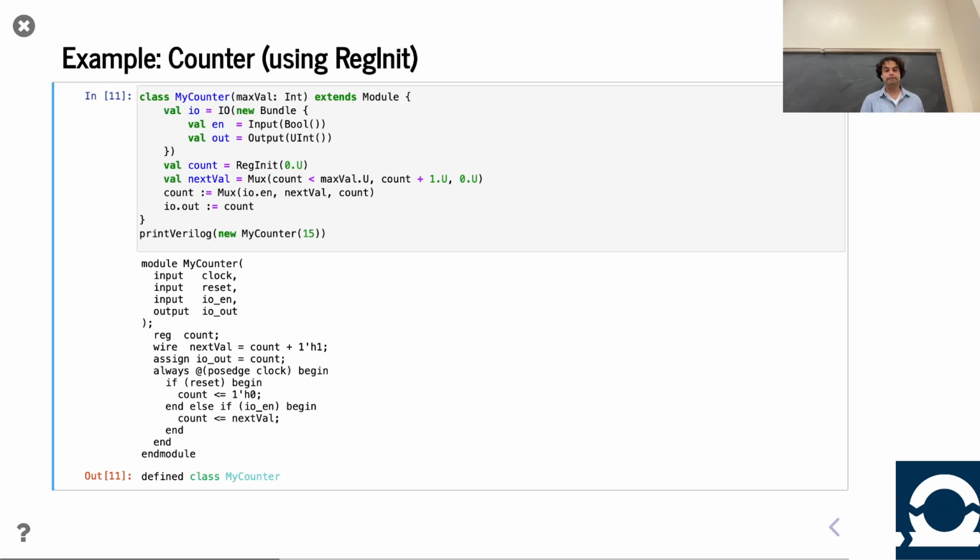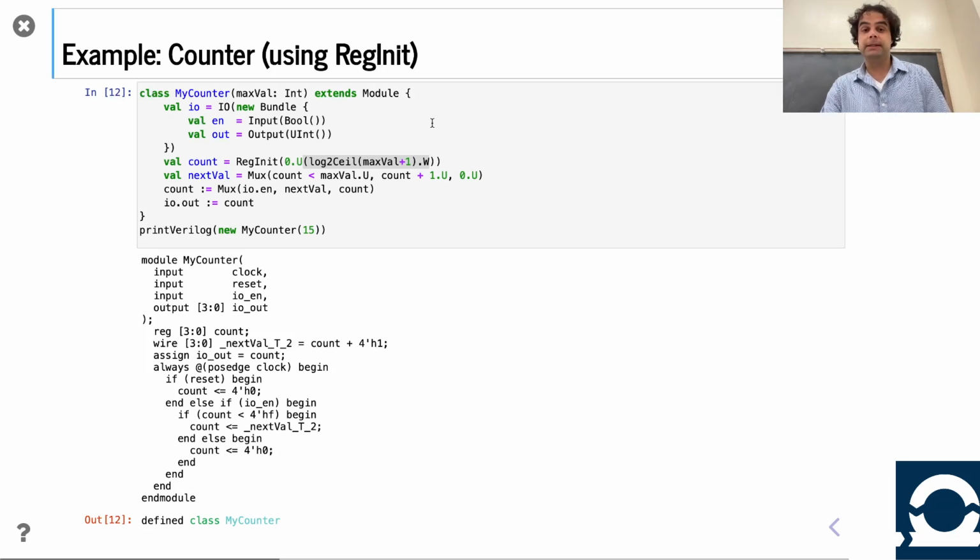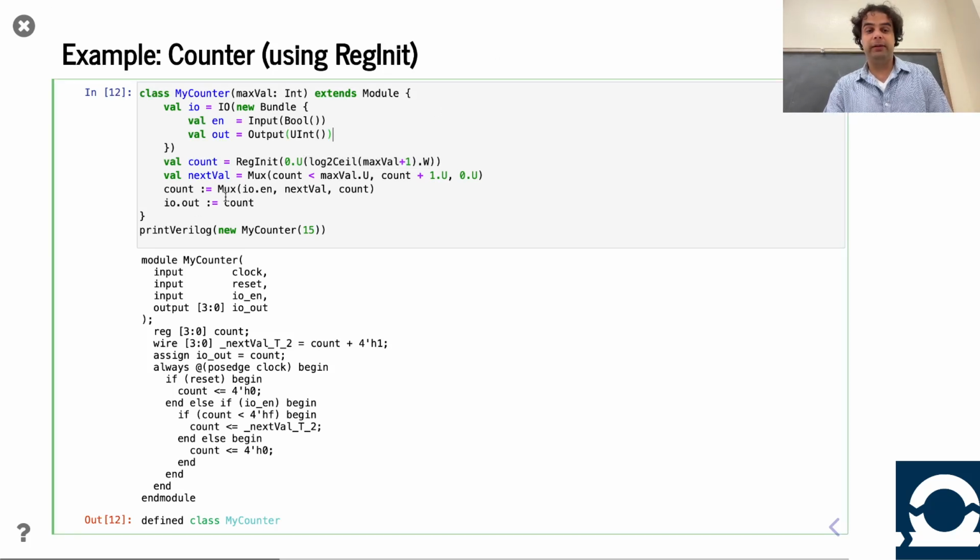It sees the other portions, and so we need this width in order to have it handle how big it is, because otherwise, without the annotation, it does not know how big to make that counter. Now, in a larger design, you may have other things in the surrounding context to give the inference tool information to figure out that width correctly. But for this counter in isolation, the tool does not know. So it can default to too small, and that's a problem. Cool. Questions? Okay, so now we're down to two muxes.